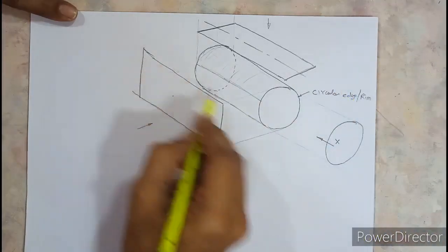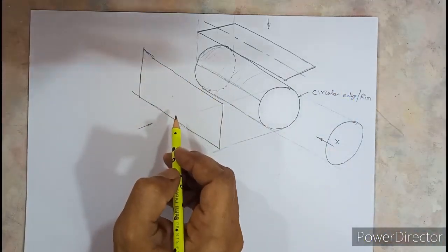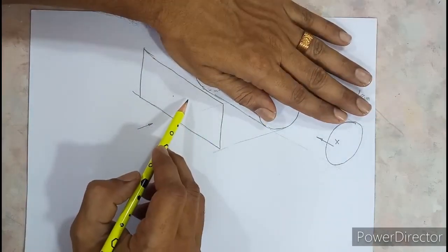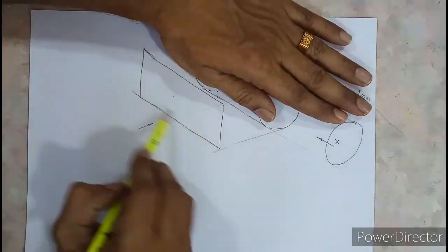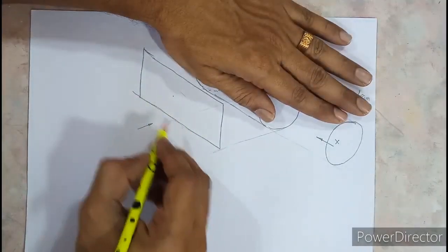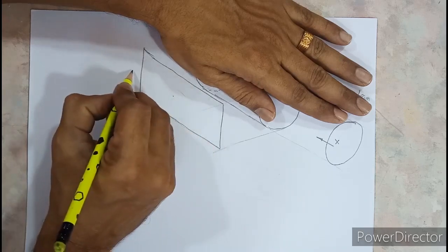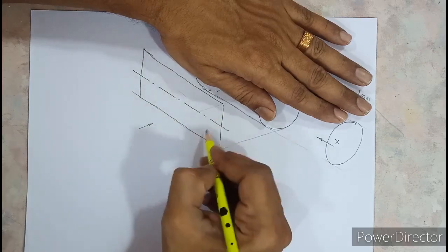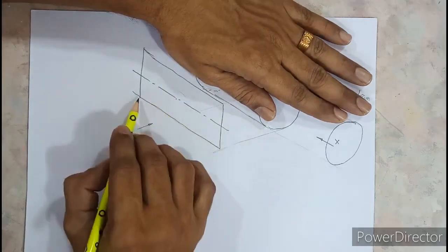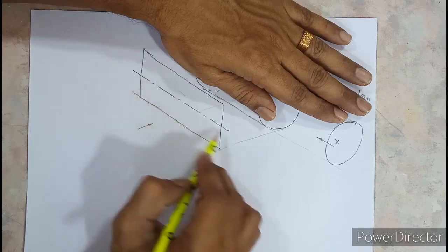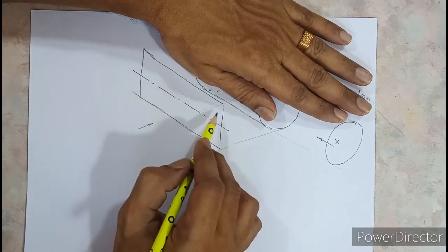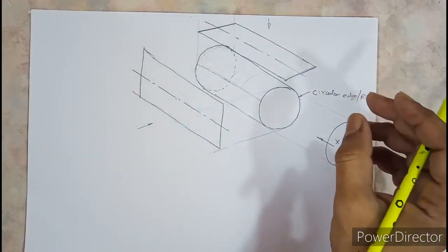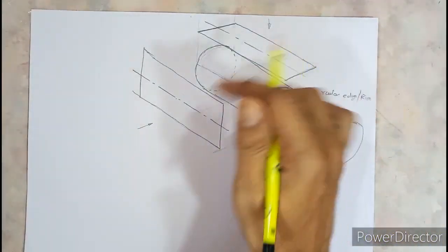Now whenever you see a rectangle, and if I don't show you the other diagrams, the confusion lies in whether the surface is flat or circular. So in engineering graphics, whenever you find a rectangle with an axis line, big dash and small dash, you have to understand that it is a curved surface. A rectangle without an axis line means a flat surface, and a rectangle with an axis line means it is a curved surface. That is how a cylinder is seen as a circle in one view and a rectangle in the other two views.